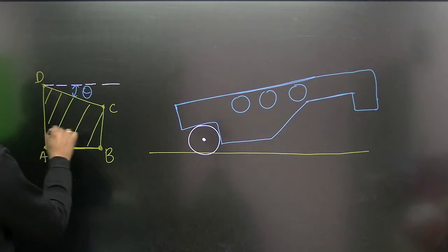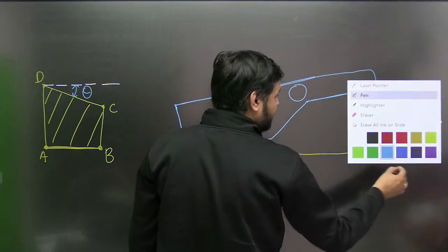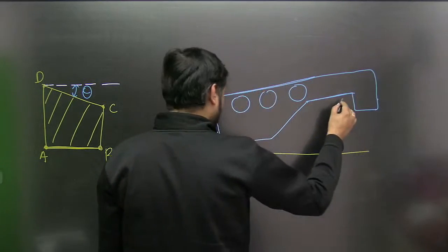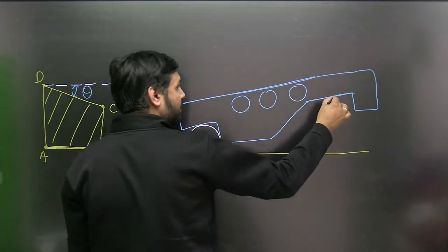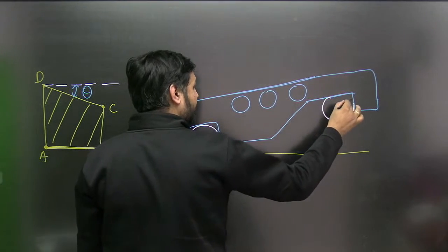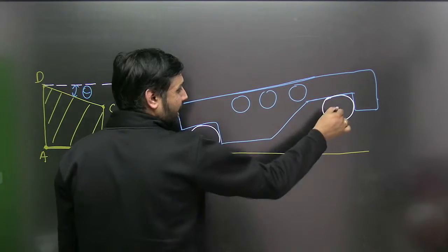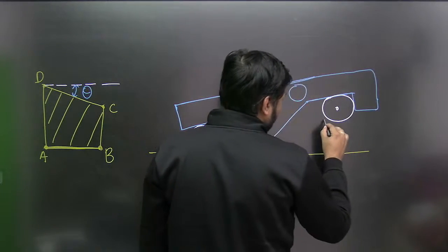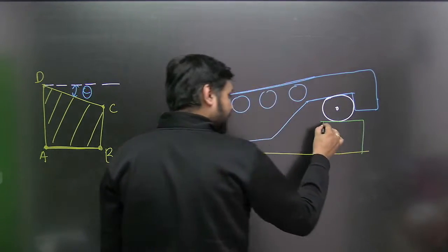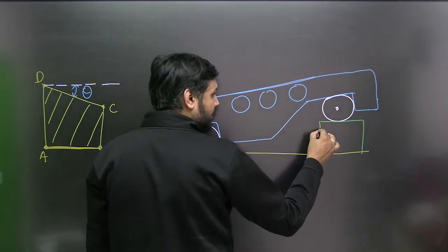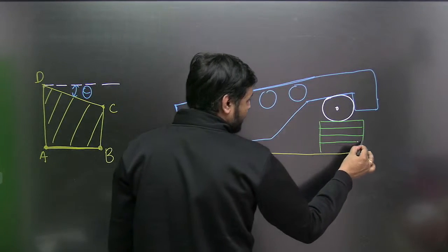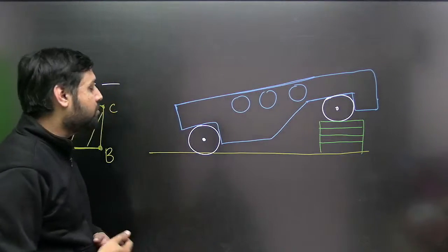My dear lovely students, here you have another roller, and this roller and that roller have the same diameter. Below this roller, what have you piled up? You have piled up different highly polished rectangular steel blocks called slip gauges to build a height dimension.